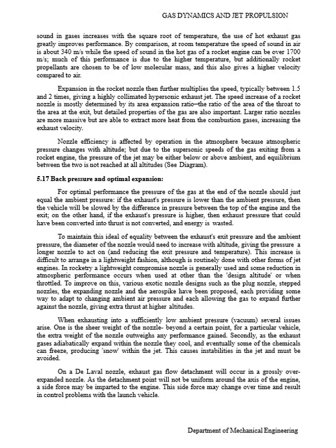Secondly, as the exhaust gases adiabatically expand within the nozzle, they cool, and eventually some of the chemicals can freeze, producing snow within the jet. This causes instability in the jet and must be avoided. Thirdly, in a grossly overexpanded nozzle, exhaust gas flow detachment will occur, as the detachment point will not be uniform around the axis of the engine. A side force may be imparted to the engine. This side force may change over time and result in control problems with the launch vehicle.